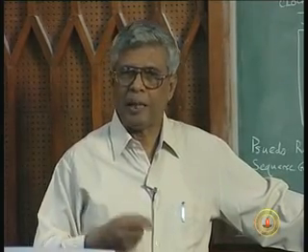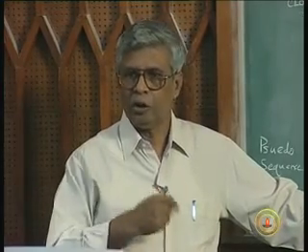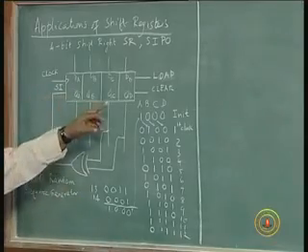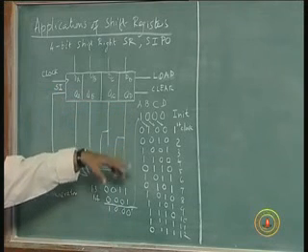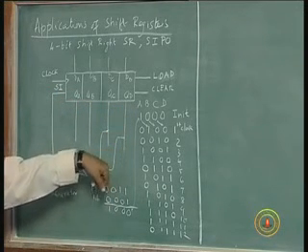But if you have this pattern that is given as a test pattern, I can use it for testing. I can give the initial pattern and send it, and then test whether I am receiving the other things in the same sequence. So one of the important applications of a shift register is a pseudo random sequence generator. And I can now have different starting values, so that the patterns will be repeated but not in the same sequence.